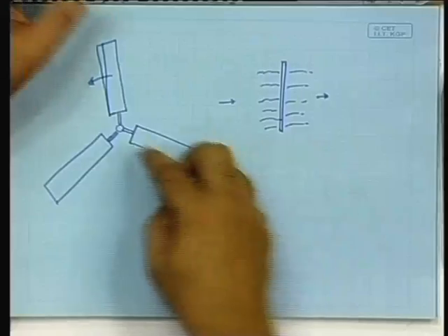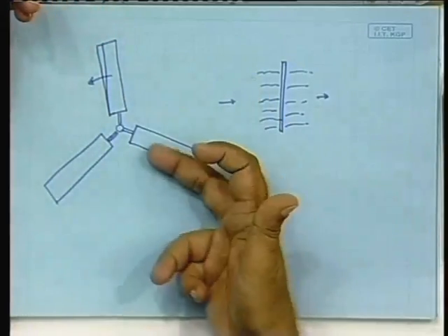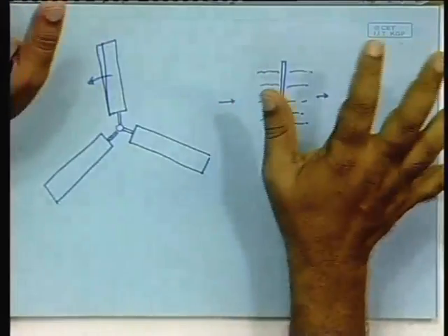And if the blades are so sparse that the disturbed wind passes and the next blade comes much later, then obviously a lot of wind will pass through without taking part in the energy transfer. So, it is clear that the optimal choice of the number of blades should be dictated by the consideration that the time taken by the disturbed wind to pass through and the time taken for one blade to come into the position of the other blade should be almost the same, clear, slightly larger, but almost the same.